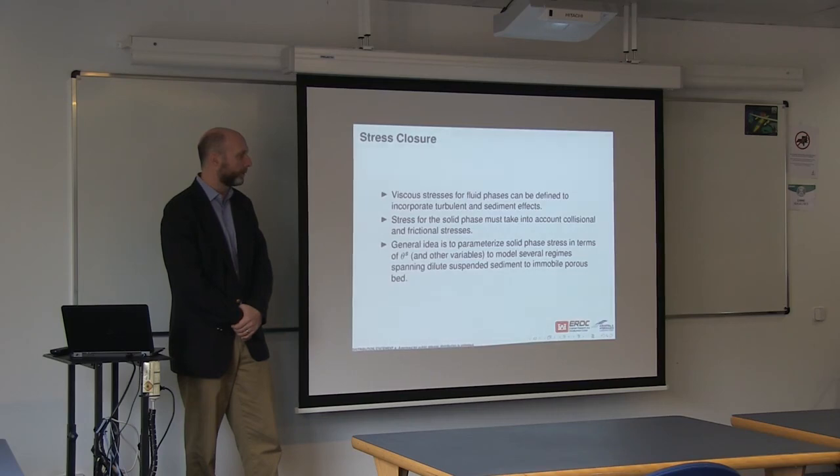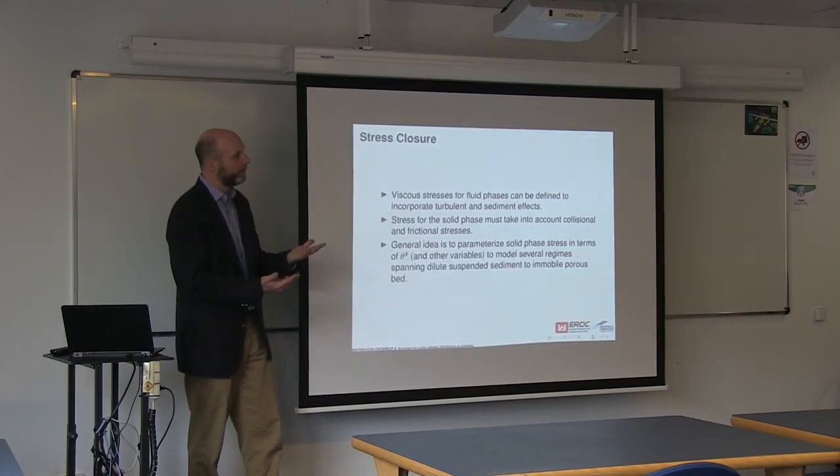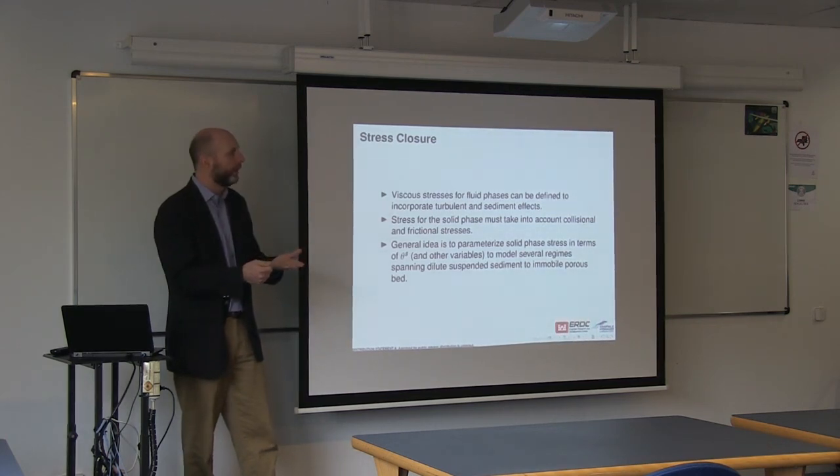That's partly because we're trying to work out some of the issues with the variations in the drag and the lift. One way of looking at this in terms of FSI is as a partitioned scheme. You do a step where you calculate the fluid flows, you integrate the stresses, you get drags, and then you take a step with a system of differential equations. And that's very sensitive to the drag forces that you calculate.